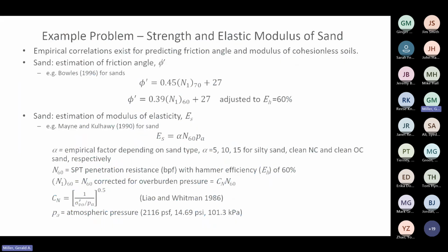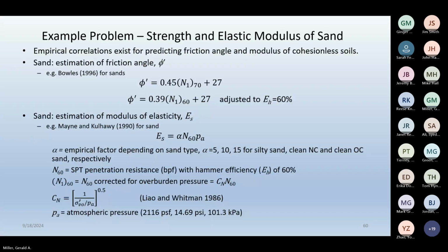And then for the other example problem, I'm going to assume a sand material, and I'm going to use N160 to estimate the friction angle. So I'm using an equation from Bowles. I'm a big fan of Mr. Bowles. I love his books and his insight. There's a lot of different equations out there. I just picked this one.